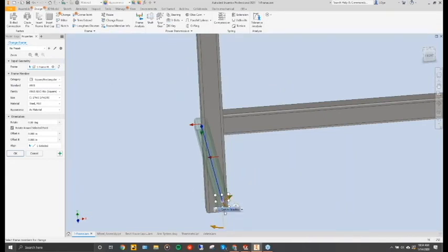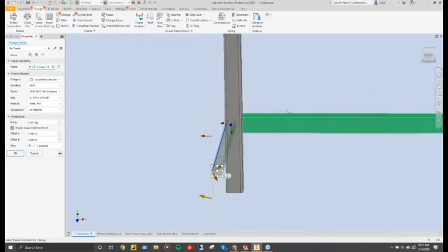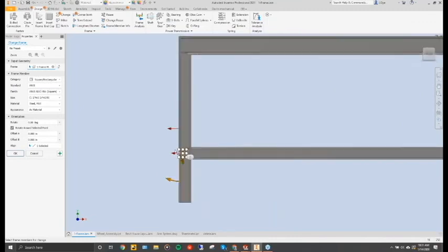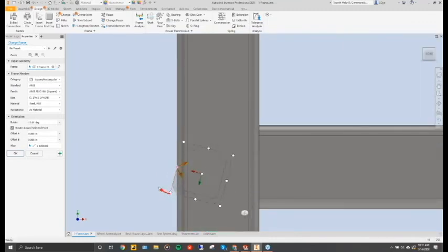If I want to relocate that, I just need to select the correct glyph, and there it relocates it. Look at it from the side, grab that manipulator, and you can rotate it around. Besides grabbing those manipulators, you can also come over to your dialog and enter a particular angle you want it set at.